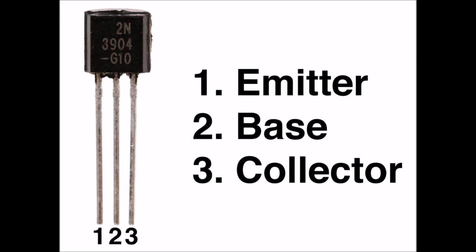Alpha. We can describe the current variations in a bipolar transistor by dividing the difference in IC by the difference in IE that occurs when we apply a small signal to the emitter of a transistor with the base connected to electrical ground, or placed at the same potential as electrical ground.